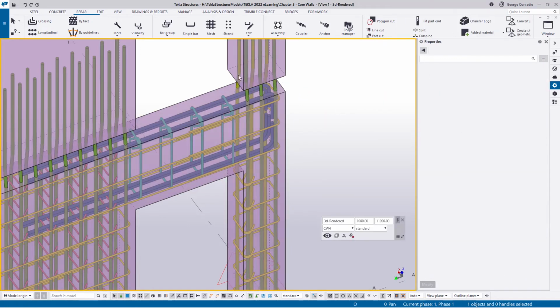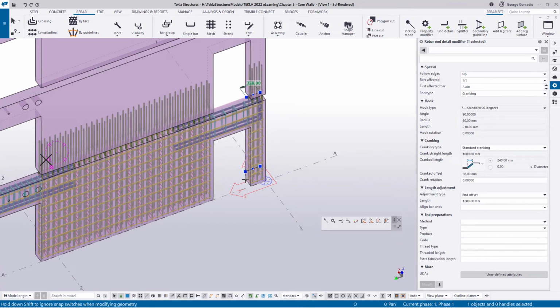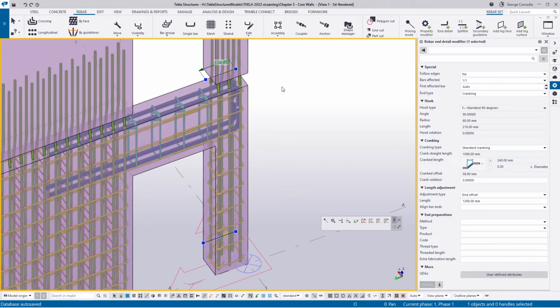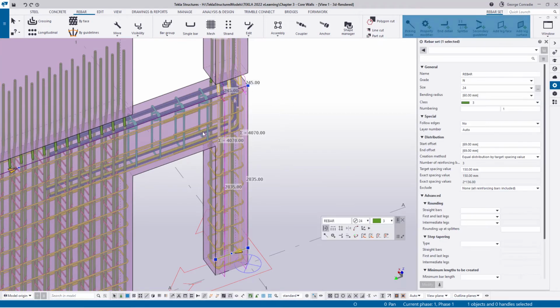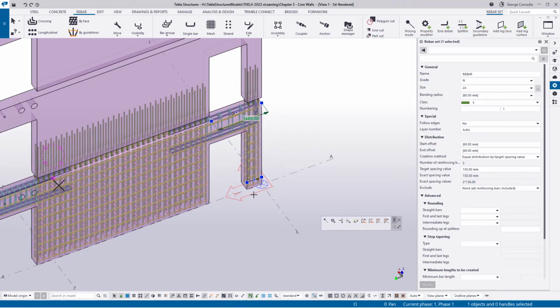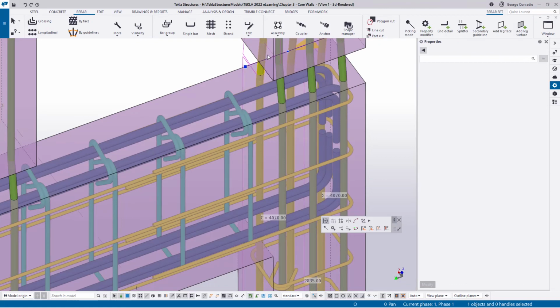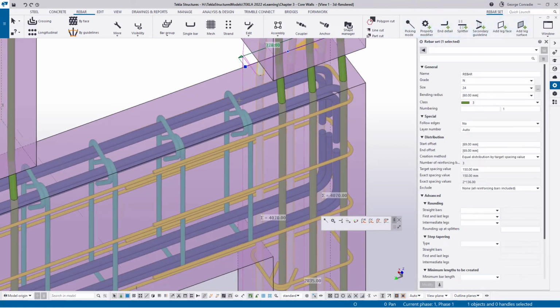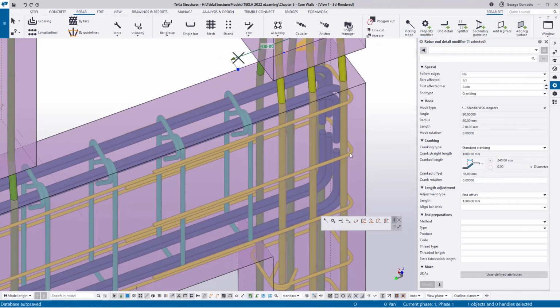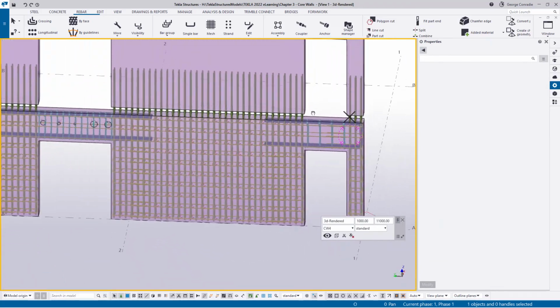And now it doesn't really influence the other bars, but just to be absolutely sure, I'll always drag them back to where they need to be. If I click on that again, if you just hover over this end and pull this arrow back to where it's supposed to start, 410. Just want to make sure that one should also be 410. So if I grab that and I hover over this point, 410, correct. Okay, so that takes care of just about that whole wall.